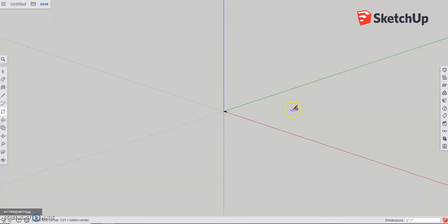You may notice that your shape is extremely small now. That's because we went from the size of a 6-foot human to about 2 inches. To zoom in, if you don't have a middle mouse wheel to scroll, you can instead come down to this tool called Orbit. Click the zoom window icon, which is the 4th icon under the Orbit tool.